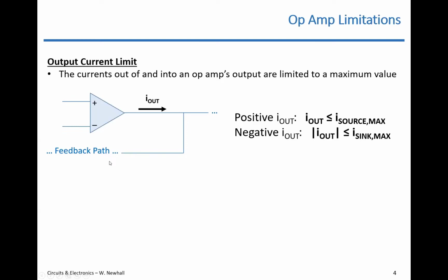So typically you use resistors in the few k ohm, greater than 1 k ohm, up to maybe 100 k ohms, maybe 50 k ohms. But if you start getting into the meg ohm and 10 meg ohm and larger, your op amp circuit won't work like you would expect. Okay.